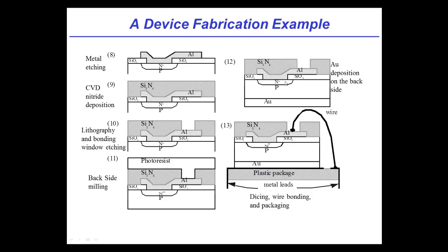So there we go. So now what I'm going to do is take this chip that's completed, I lay it onto a printed circuit board with a metallized pad on the bottom, and then I run a wire bond from the top to the bottom, and now I have my two contacts. Here are my two leads, and I have a diode. Now, there's lots of cool things about this. I mean, this is a very simple process. We didn't use it to make a transistor. We used it to make a simple diode.